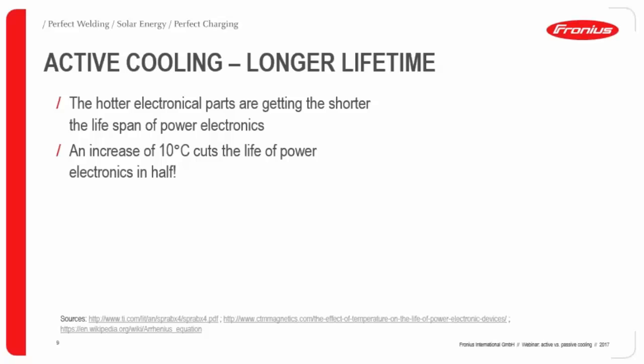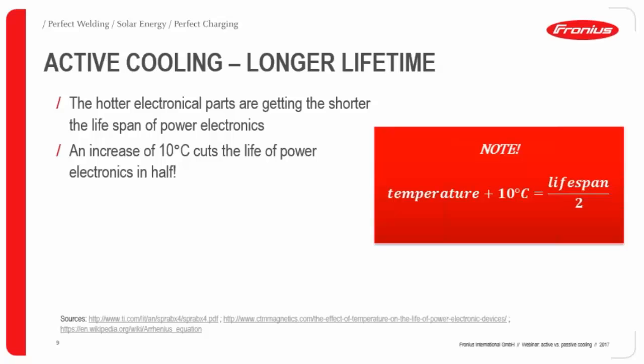And that is, if you increase the temperature by 10 degrees, then that can cut the lifespan of an inverter or power electronics by half. And I would say that is a really strong argument, because imagine you have got an inverter in the typical surrounding where you've got 25 degrees. That has very much a difference in the lifetime.